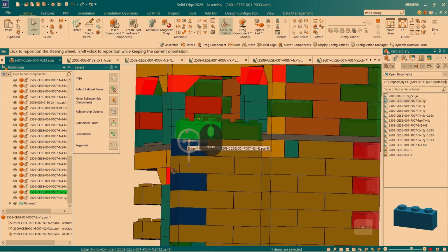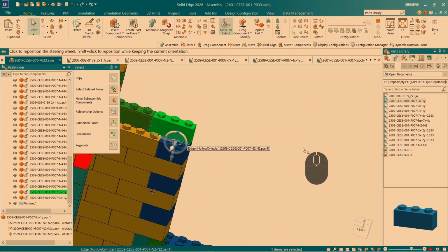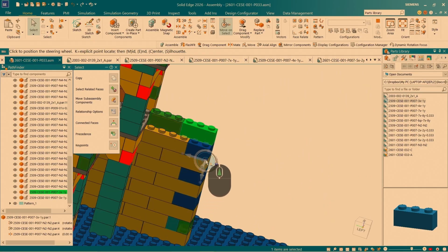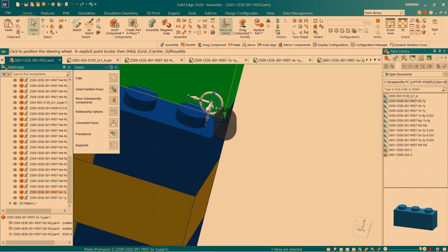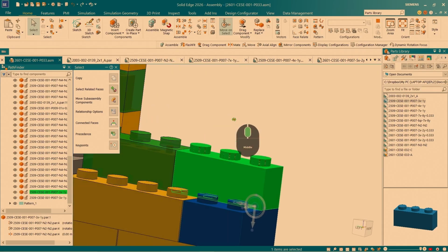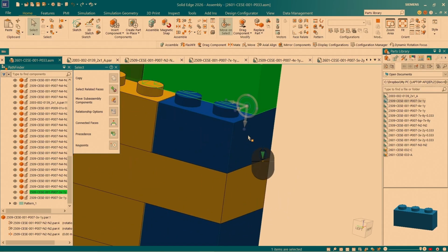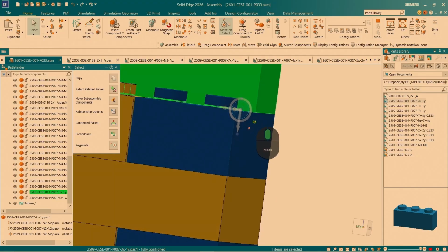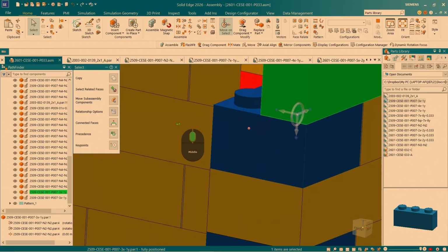Instead of looking in, I'm going to try looking out because we won't be picking up on anything on the base plate. And again, I'm going in here, and that looks good. So I'm going to click there, and now I'm just going to change the orientation to see, yeah, that looks like it's level with the top face of the part.